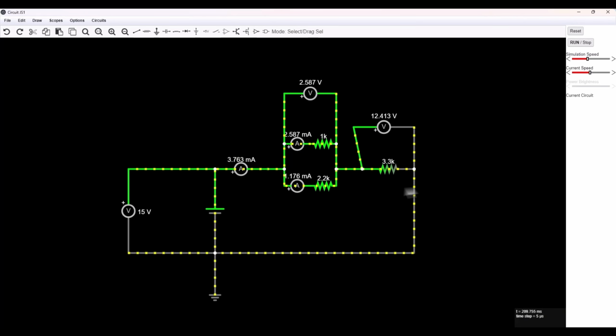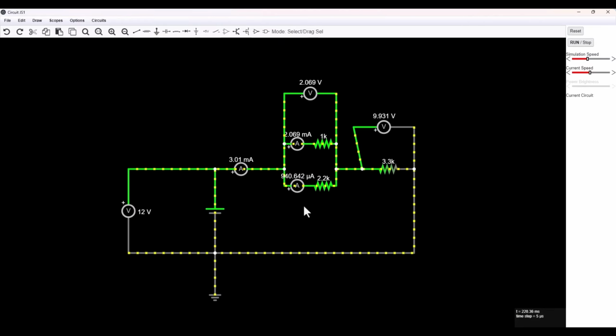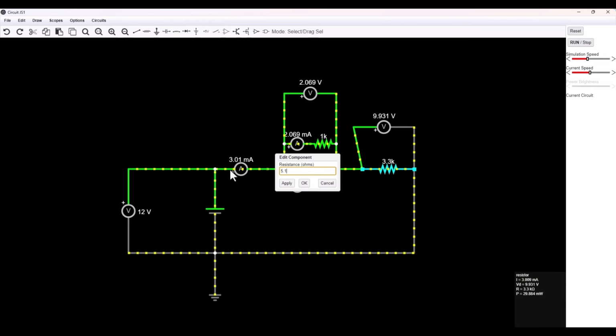For the next part, we do have a little bit of changing. Our resistor is going to be some kind of series resistor, and the parallel resistors should be at this point, which is still going to be the same, but the numbers are different. So V1 should be 12 volts. We are still going to use the previous one. R1, which is in series, should be 5.1K. Then R2, on the top, should be 1K, still 1K, and R3 should be 3.3K.